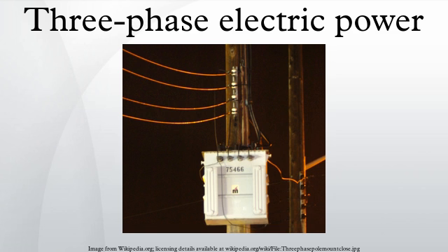voltages. Alternatives to 3-phase: split-phase electric power is used when 3-phase power is not available and allows double the normal utilization voltage to be supplied for high-power loads. 2-phase electric power, like 3-phase, gives constant power transfer to a linear load. For loads that connect each phase to neutral, assuming the load is the same power draw, the 2-wire system has a neutral current that is greater than neutral current in a 3-phase system.